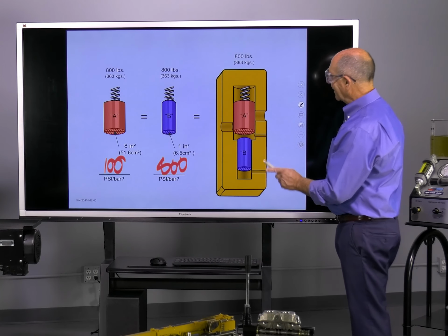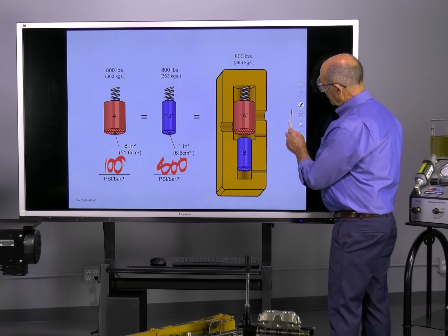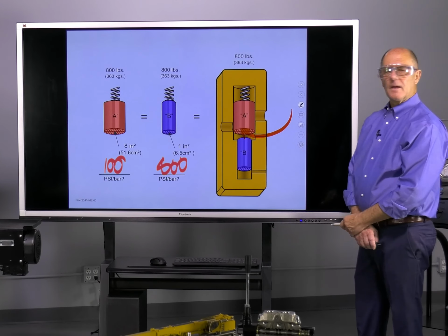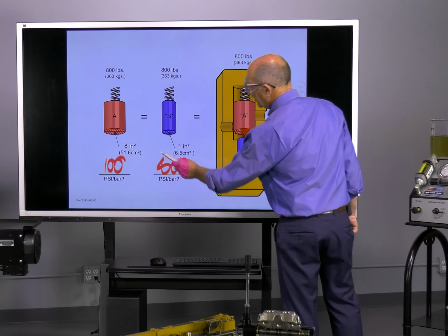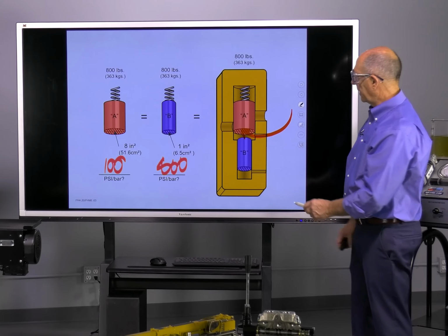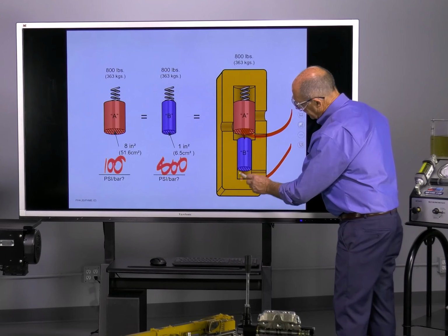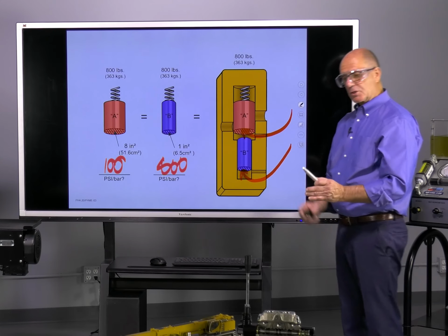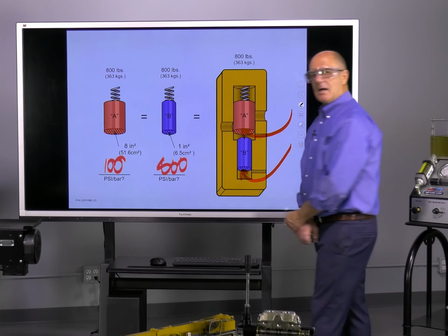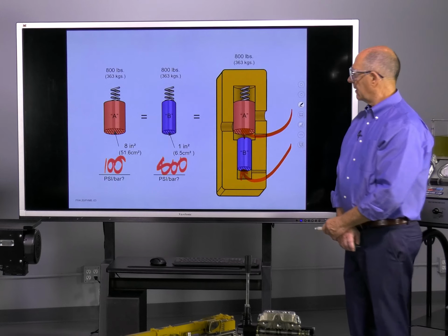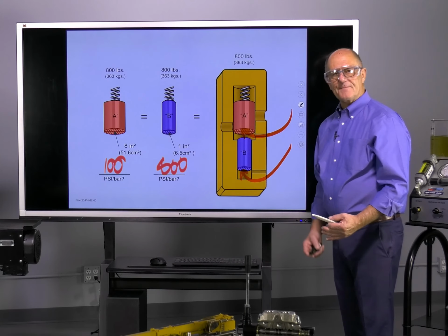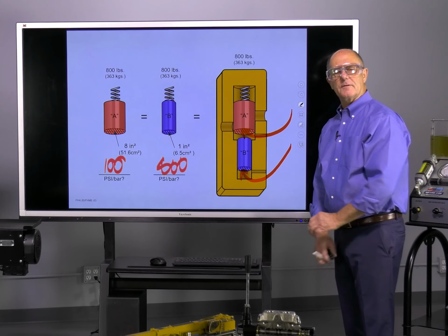When we bring oil in to the bottom of the large piston, it will require 100 psi to open the valve. However, if I bring the oil pressure in to the small piston, it will require 800 psi to open the valve. What have I just done? I've built a pressure relief valve that will open at 2 different pressures.